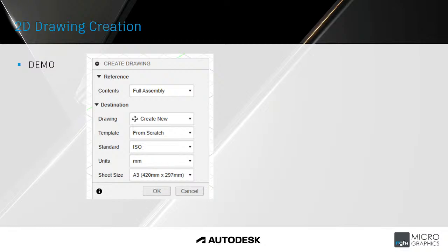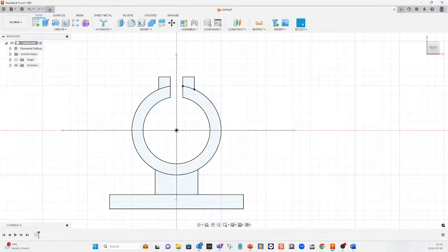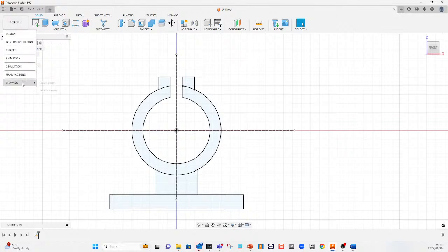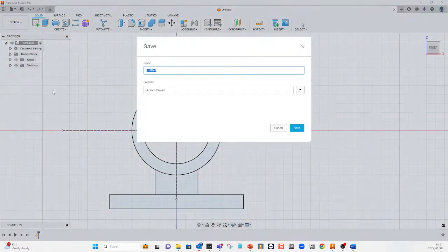After the drawing, we want to obviously get the sketch on a drawing sheet. How do we get the sketch on the drawing sheet? In Fusion, we change the Design tab. We just click on it and go to Drawing. We go and we select the From Design option.